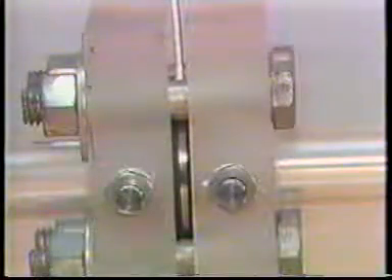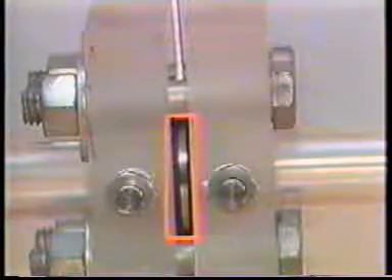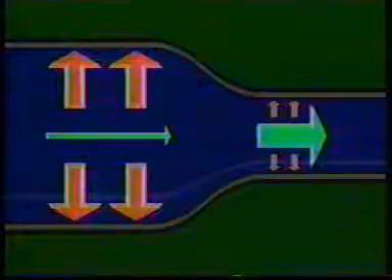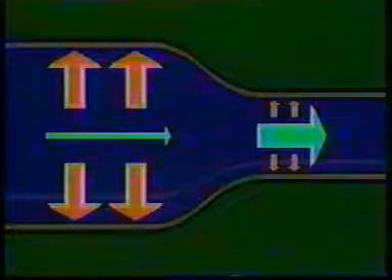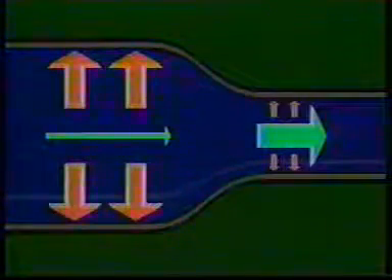When a fluid passes through a constriction, the flow velocity must increase if mass flow rate is to remain constant. To accomplish this, the same volume of fluid will pass by points A and B within the same period of time. But in order to do this when the size of the passage narrows, the fluid must obviously flow at a faster rate. Except for energy lost through friction, which we will not consider here, the total energy of the